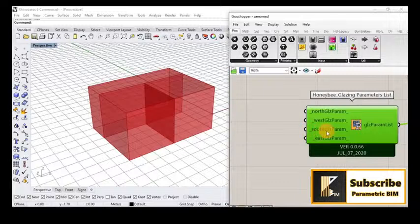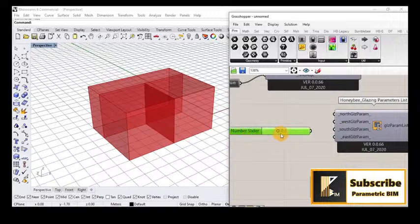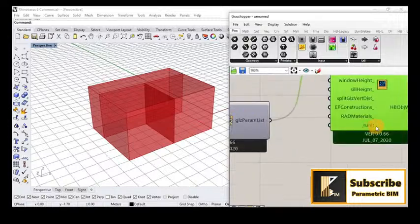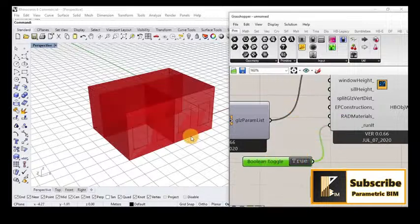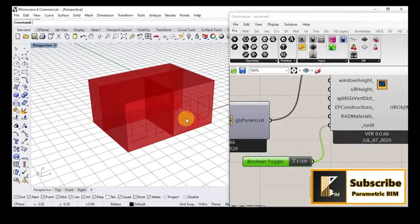I need to assign a parameter or number slider for the south elevation parameter. I will go with 0.3 for the glazing ratio, and now we also have to run it by assigning a Boolean toggle here.